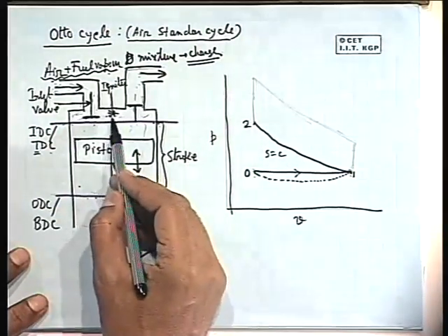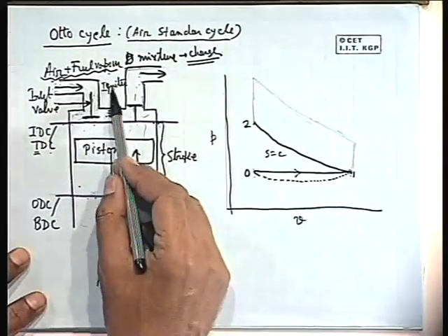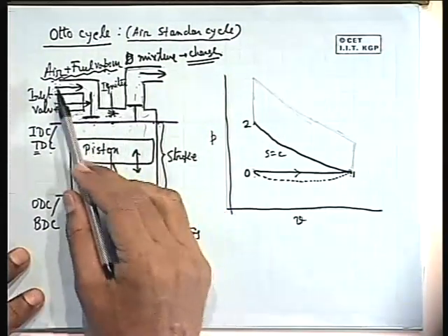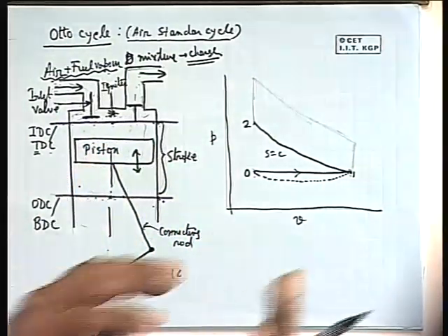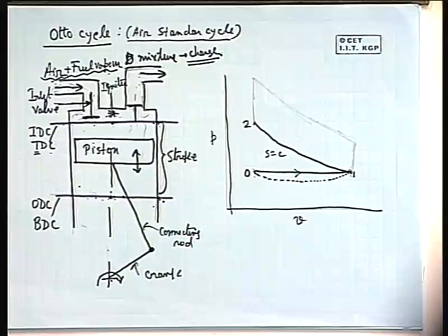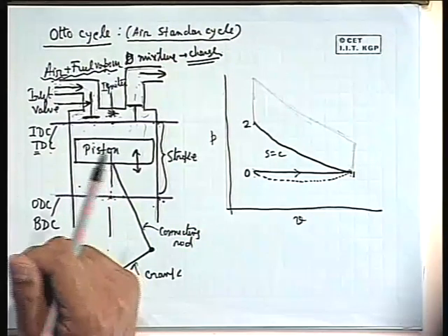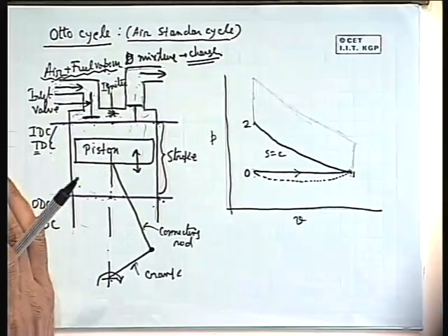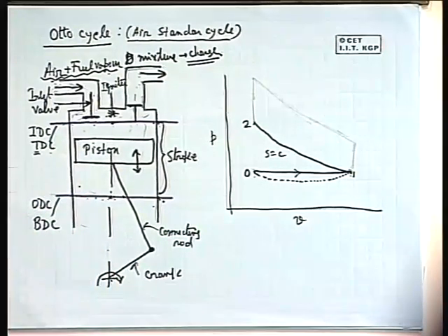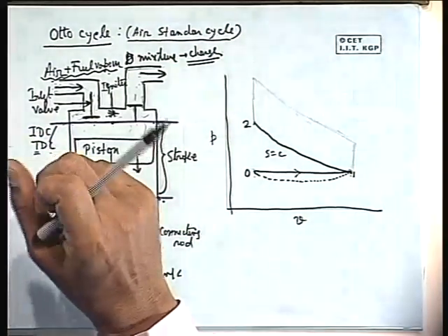Then when the burning takes place, this is very important, when the igniter burns this mixture, the air and fuel vapor are so thoroughly mixed before being admitted to the chamber, which is done in a device known as a carburetor. The fuel used is petrol, which is so highly volatile that it is easily made into vapor and can be thoroughly mixed with the air, so that the physical contact is very good, and immediately after ignition it releases the heat, which is a very colloquial term. It makes the combustion complete and the pressure and temperature are instantaneously raised.